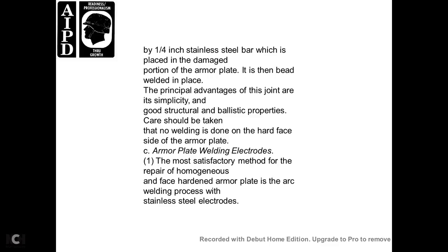Care should be taken that no welding is done on the hard face side of the armor. The armor plate welding electrode is the most satisfactory method for repairing homogeneous and face hardened armor plate, using the arc welding process and stainless steel electrodes.